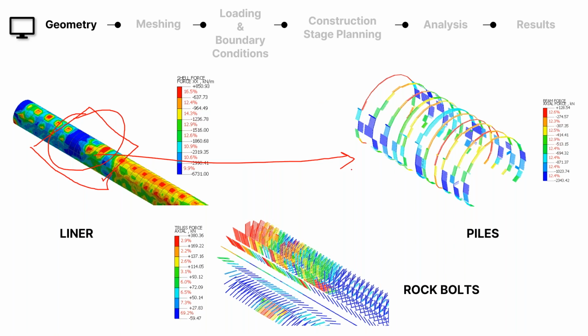So you can say this is a systematic bolting pattern, but again that has been improvised depending on the area of interest. Now, you can also say that yes, we have done a numerical model and we can see the results, but again, when I went to the site, or when anyone else from your team, or let's say my team, went to the site, they saw some extra areas that had some loose wedges that they wanted to seal off. So yes, you can also apply a rock bolt in there, but again that is a completely field observational method.